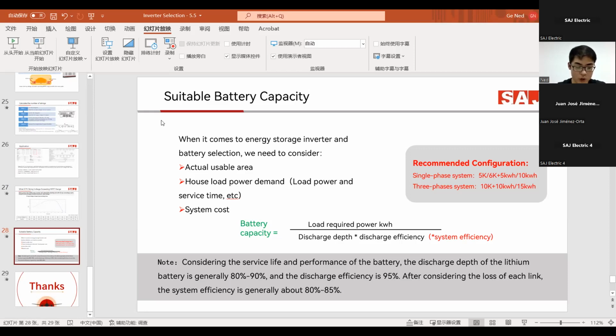For example, if you have a 5 kilowatt solar power plant on your rooftop, with an average of 4 hours of equivalent power generation, and you take an 800 ampere hour battery, the maximum charging current is 100 amperes. In backup mode, the battery will need 2 days to be fully charged.